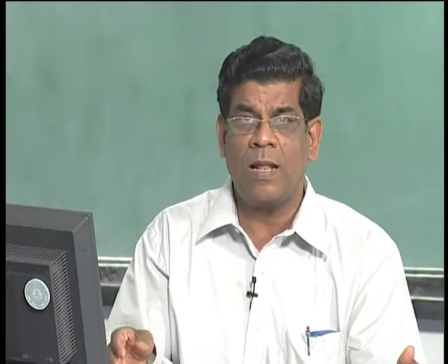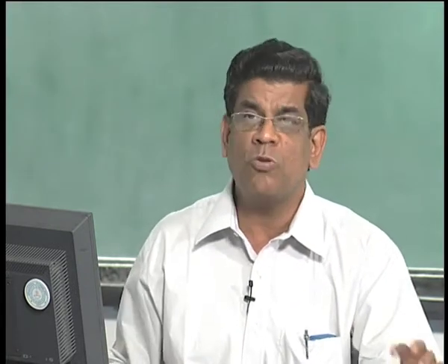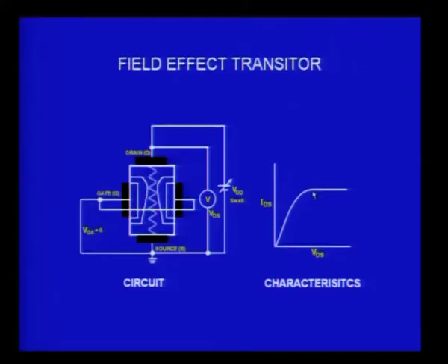So, there is a repulsive force from inside, the electrons flowing in the channel, and there is a crowding effect due to the channel depletion layer keeping increasing in width. So, you would find there will be an equilibrium at some stage due to the external pressure and the internal pressure. Once the equilibrium is reached, no effect of the voltage will be felt, and therefore the current will become a constant. You cannot increase it or decrease it, it will come to a saturation.